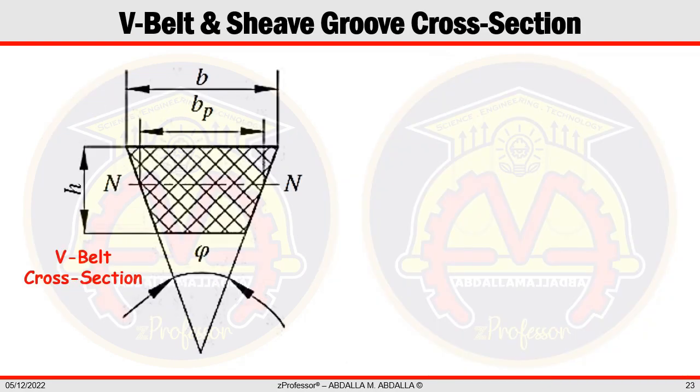The range of industrial uses for V-belts may be the greatest of the belt kinds listed above. The reliability and life of various V-belt designs have been extensively tested and standardized. The belt industry uses the datum width system for both standard and narrow V-belt arrangement. The pitch line indicated in the diagram as NN serves as the belt section's neutral axis. As the belt curves around sheaves, the pitch width BP, also known as the pitch line width, remains constant.